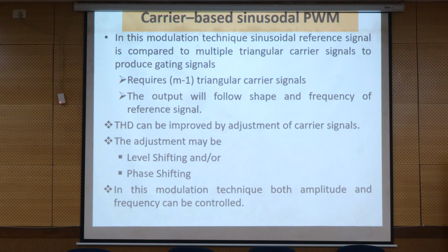If you want to generate a pulse, a PWM signal, for your inverter module, for your power semiconductor switch, what signals are required? One is the reference waveform and the other one is the carrier waveform.